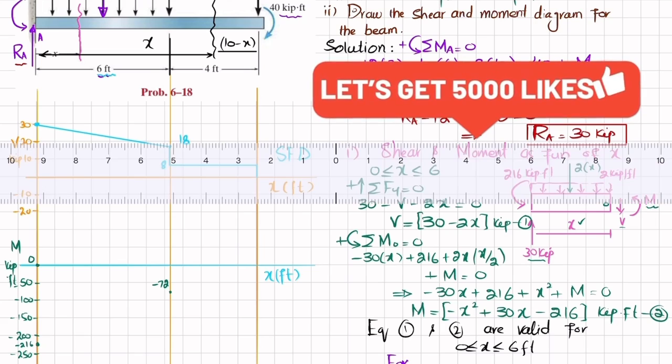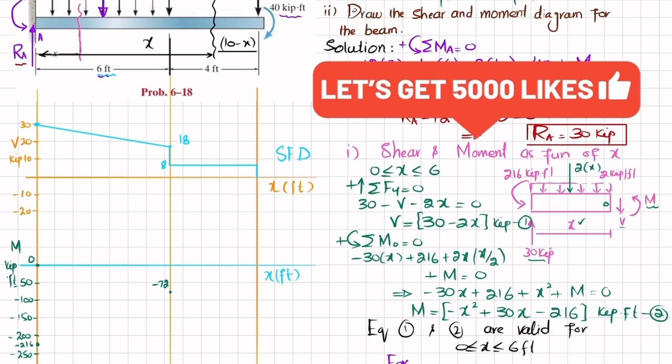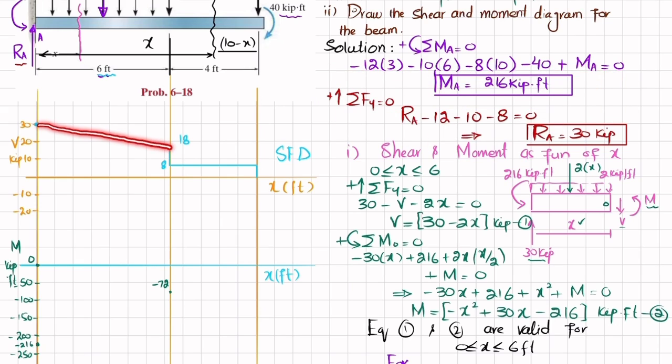Clear? Now you can see that this shear force is a linear line of first degree and the slope is decreasing. So the bending moment will be a second degree line and it will be counterclockwise like this. Clear? So we will join these 2 points like this. It will be a second degree line. Clear? This will be the line.